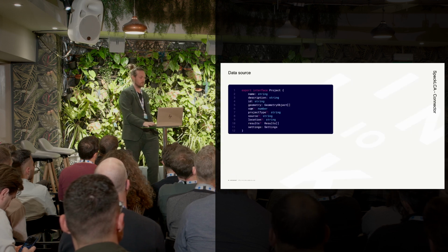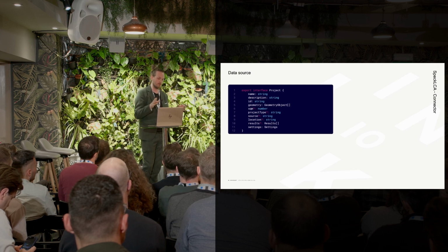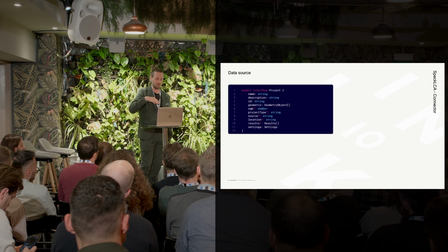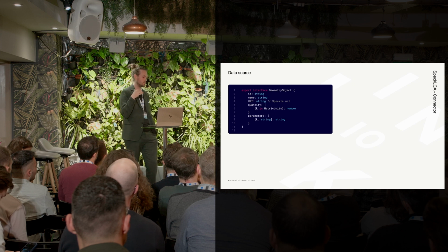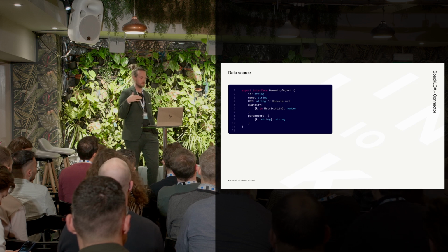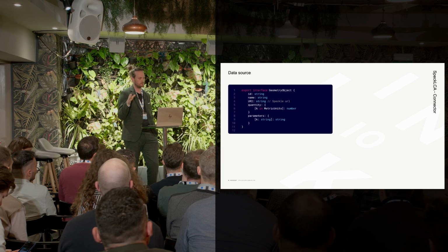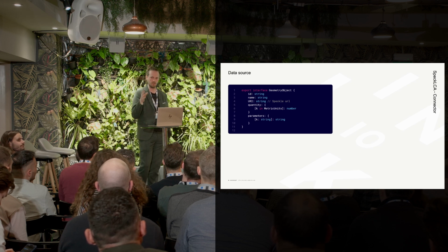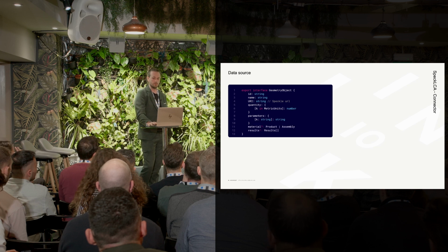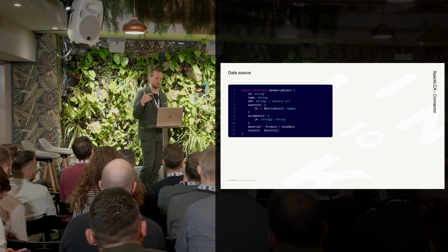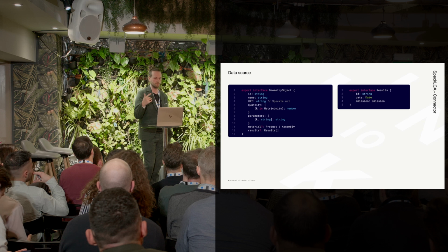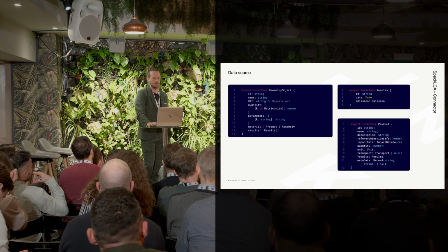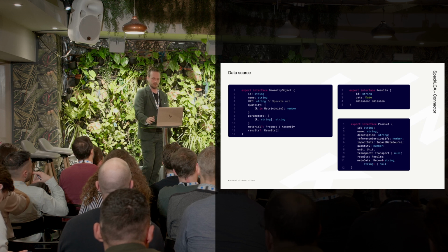And the geometry objects: first we have a project, and inside of that we have a focus on how our project is built up, because you need that for many things, but let's focus on the geometry objects here. It's a very simple structure. We just have an ID, a name, and a URL, and the URL is actually the Speckle object. We take out some quantities just to have them in the same place at all times, because when you're sending from different applications, they get mixed up a little bit, but we convert it. And we made this so we can extend these objects. The geometry object can be extended if you want to add a material or a result to it. You just simply push another property towards it. And all of these have metadata attached to them.